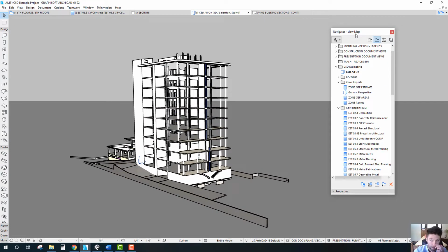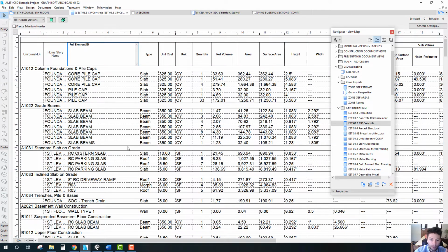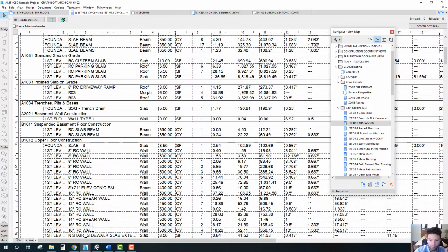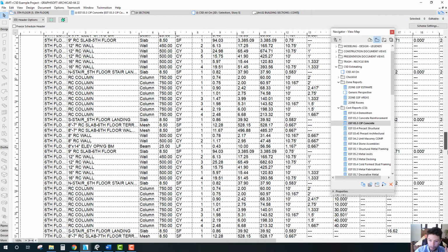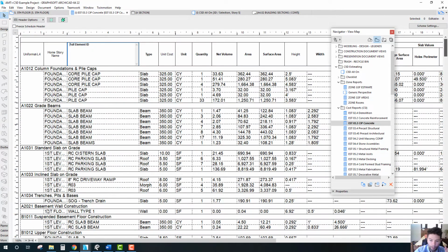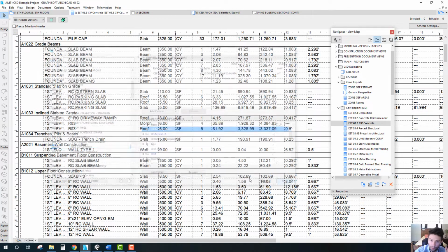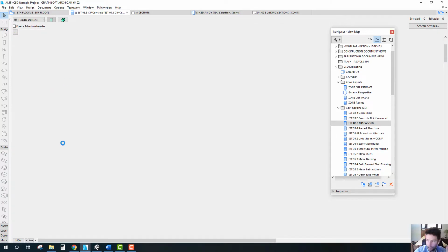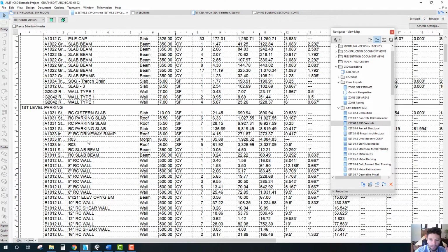So these reports can really be a really powerful quality control tool for just going through and reviewing model elements and making sure that they're on their right layers. You know, in this case, if I went through here to, let's pan down here a bit. We got a lot there under the upper floor construction. Perhaps there's a better way of looking at this if we say instead have our home story at the top and then our Uniformat classification. This would be another nice way of just organizing our model and our view of the data that makes up the model. So we'll let this finish real quick and we'll see this by story.